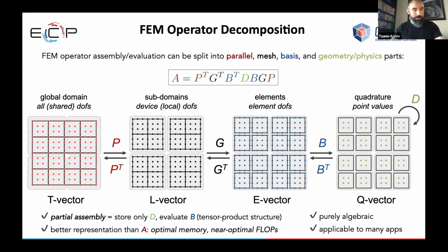We assemble it, we use an iterative or direct solver, and that's it. But that's not sufficient for performance, and that's not sufficient certainly for harder methods. What is more useful is to think of a finite element operator A as a sequence of variational restrictions with kind of gather-scatter type operators.